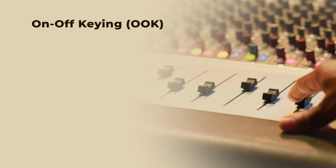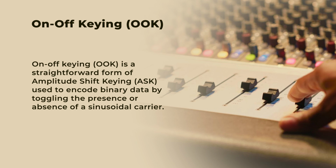The next topic is on-off keying, that is OOK. On-off keying is a straightforward form of amplitude shift keying used to encode binary data by toggling the presence or absence of a sinusoidal carrier. For instance, during a bit duration TB, the presence of the carrier can represent a binary 1, while the absence can signify a binary 0.